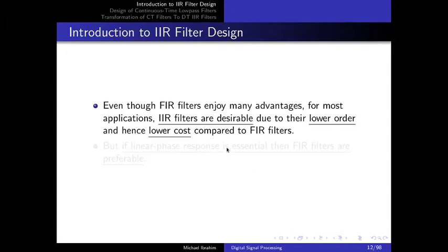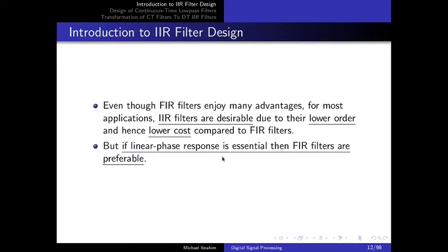So even though the FIR filters have many advantages, for most applications IIR filters are desirable because you will be having a lower order filter, less hardware, lower cost, and so on. Unless the phase linearity is a requirement for your design. So if you need to have a linear phase, if it's an essential part of your design, then you must use FIR filters.